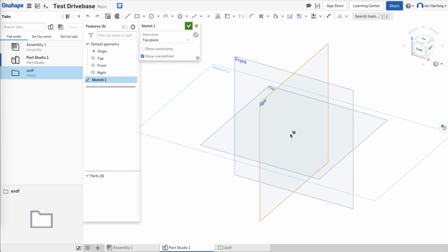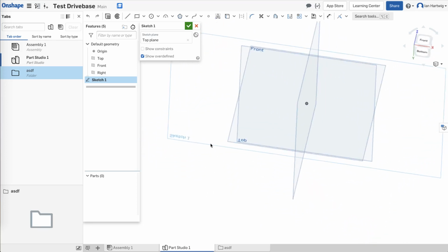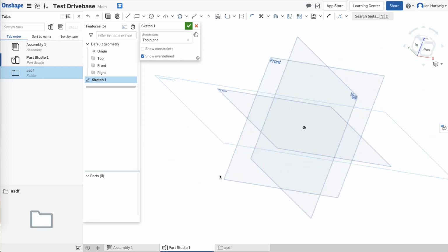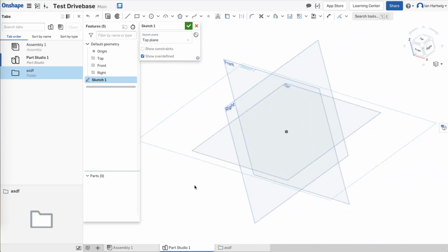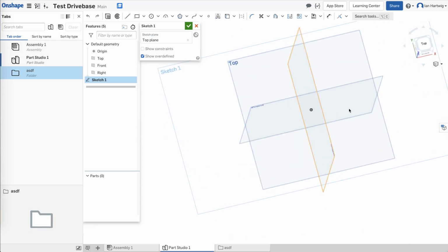It's a little bit weird to look at it like this in 3D space, so you could rotate yourself up to the top. I can do free movement by clicking the right mouse button and then dragging around. This is a little bit different than the SolidWorks command. If you're used to SolidWorks, there's apparently a SolidWorks scroll mode that you can use, but I'm not using that here.